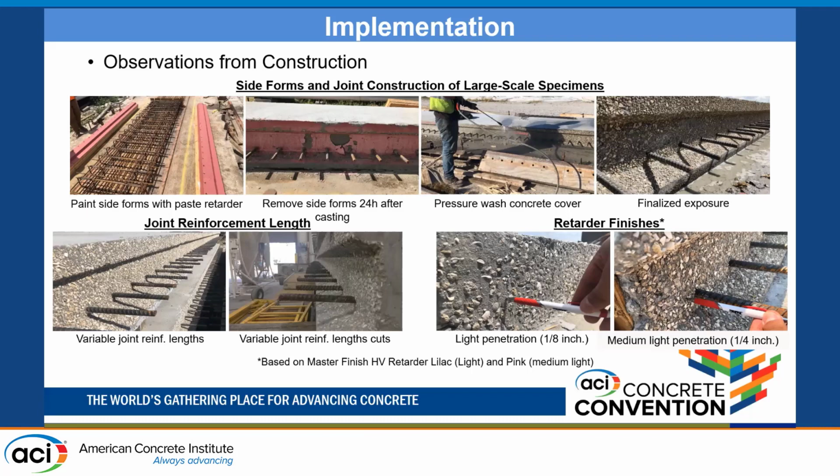Also, for the joint reinforcement length, we observed some variations of the rebar. We want to make sure that those rebars are approximately the same length. However, we didn't see any impact in the joint performance due to this small variation, even though some of those rebars had to be cut in the lab before casting the joint.